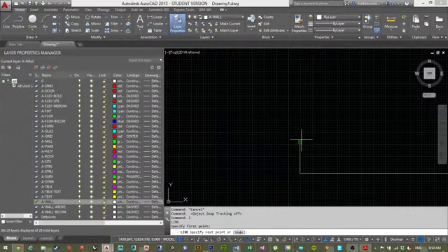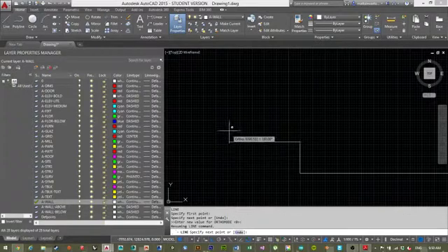All right, sorry. It's snapping to this vertical just because I've drawn this line here, but the other ones it doesn't snap to. So I would usually keep polar on, or else your building will be slightly off. It is physically impossible to draw a line perpendicular to that without it. Or I guess shift. Shift will keep it to ortho.